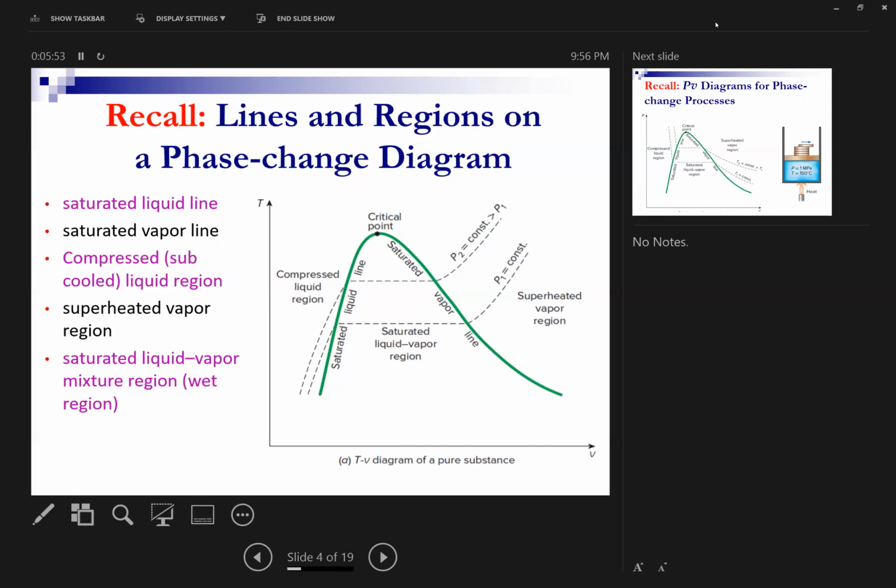And then by that, we found the isobaric process lines, which are the dashed lines shown here. If we repeat the experiment for several pressures, then we will be able to have lots of these lines. Then by connecting the breakpoints of the lines, we will be able to find the saturation dome. And this saturation dome is a very important graph for thermodynamics.